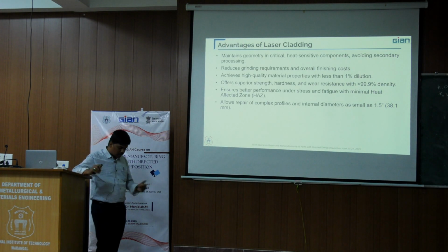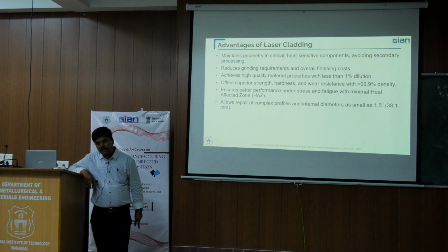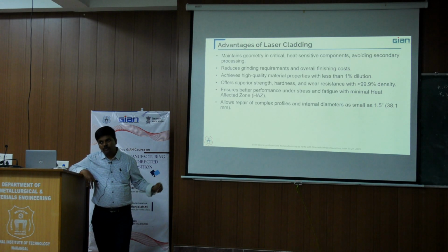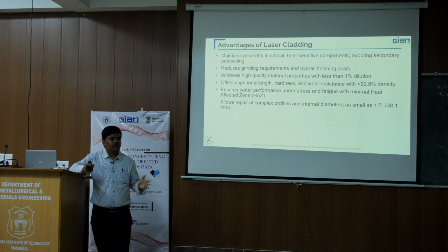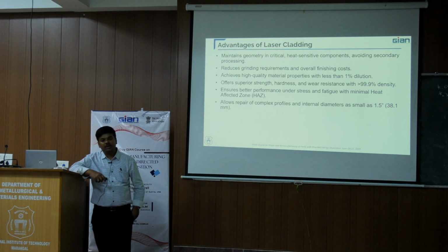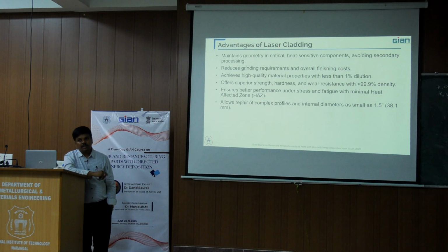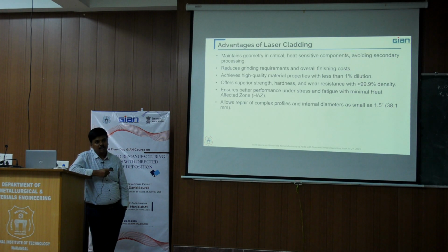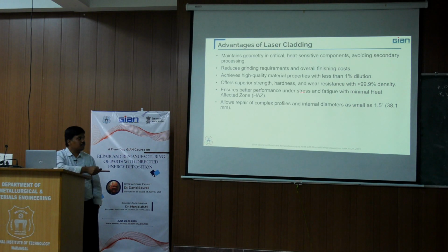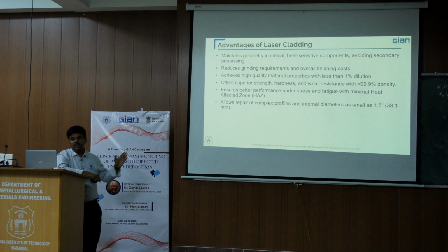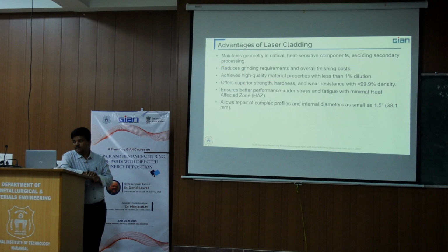We might have some thoughts: can we repair even with welding? With the TIG welding process we can repair it if a very big part is worn out. Yes, we can repair it, but the heat affected zone and the thermal distortions are greater in the TIG welding process. There we can have a lot of difficulties with the mechanical properties of the repaired parts. That is where we can use our laser DED process. Even small internal diameters of less than 1.5 inch we can repair with the laser DED process. That's what is possible with the DED process.